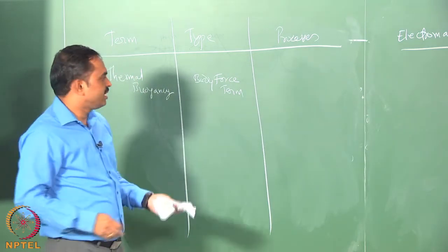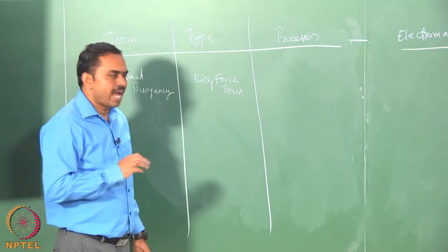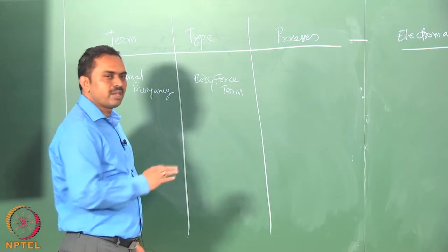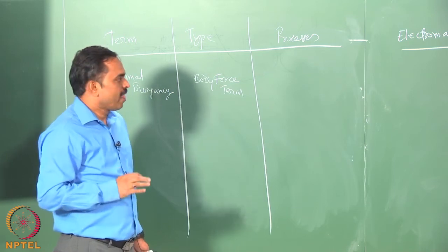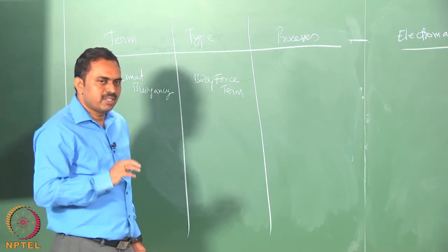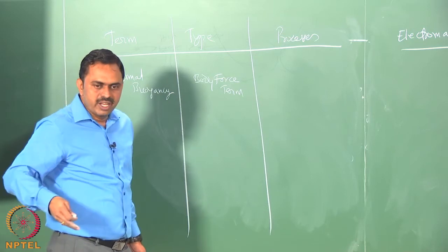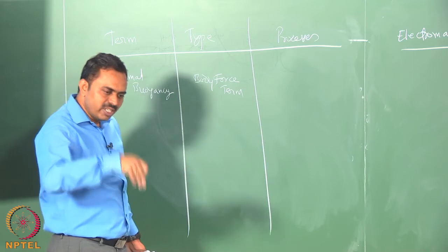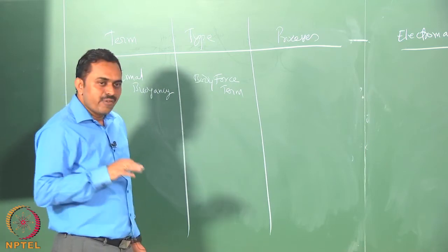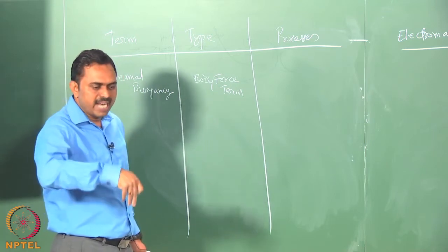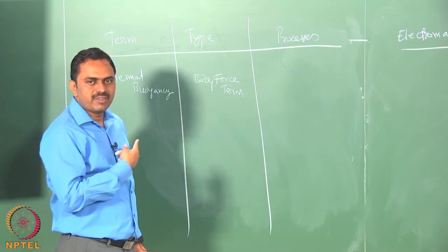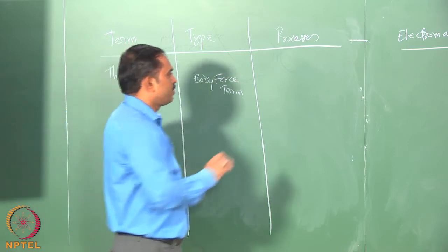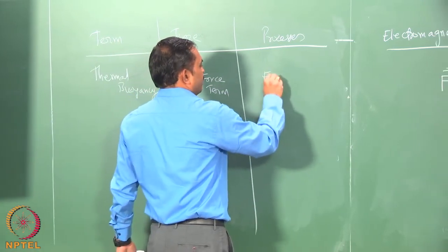And what processes is it relevant? Actually, any process that is happening on earth where the acceleration due to gravity is present, then this term should be valid. It must be present everywhere. But we must pay attention that most of the times the welding is done in a flat geometry, so that the highest temperature is on the top and the gravity is actually downwards. So, in other words, when you change the geometry from flat geometry to overhead, the buoyancy convection is going to play a role. It is not acting in the same direction. So, pay attention to the geometry, but otherwise it is everywhere effective.